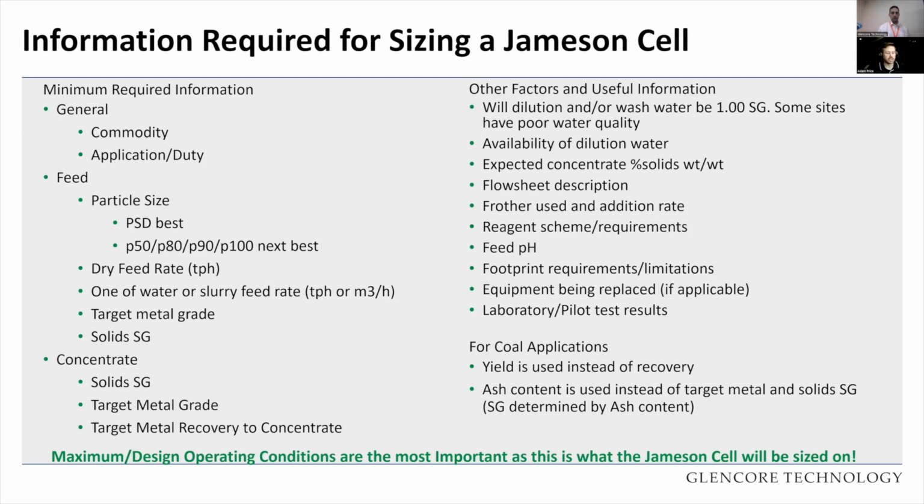And then probably the most important thing is that we always size on a maximum or a design case. So we look to produce mass balances and the complete sizings, and the key one at this stage is the maximum or design scenario. This is pretty obvious, as you want to make sure that the cells selected can deal with the absolute maximum scenario that the feed may present to the cell.